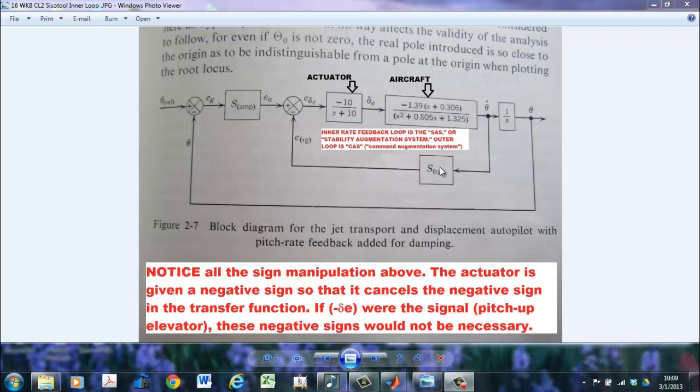And we might want to re-look at that and try to get that loop closer with more damping for the outer loop closure. But we used 5. That loop's going to be always closed, and the pilot will fly that loop. When he hooks up the autopilot, then a switch will be closed, and he'll integrate pitch rate to theta and feed it back to a theta command. And he'll want that theta to be following the theta command.